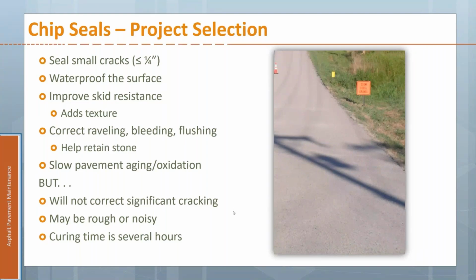You can do this, like to upgrade a gravel road to a chip seal road. That's usually going to require a double chip seal for your first go at it. But there are lots of cases where we've got a paved road that's had a traditional hot mix surface and it's just not doing that well, and we don't have enough funding to be able to come in and do a full overlay, but you can do a chip seal. And so it's still going to help preserve the structure and the surface that was there before. It's just going to look different, have a little bit different texture.